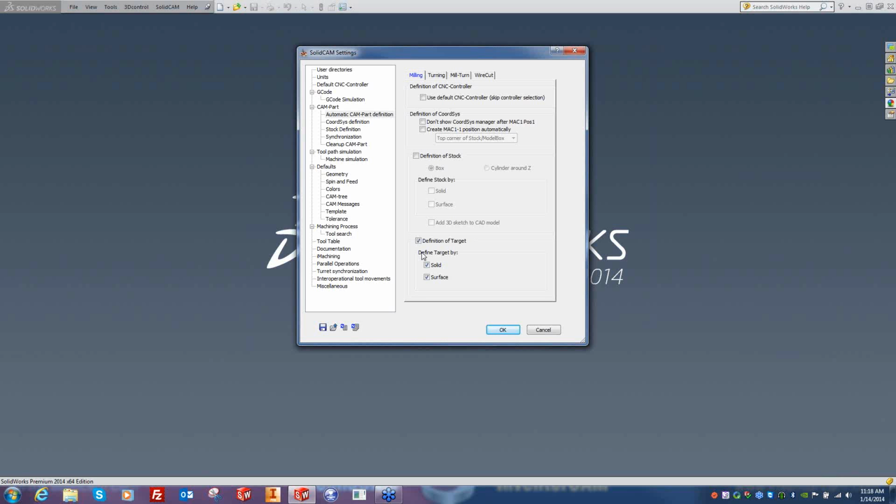But the part that you're working on is called the design model, and it's in perfect reference to the original. So if anything changes on the original, it updates the design model automatically. So, like I said, most of you probably will work with just one part at a time, and then you don't have to think about any of this. It's going to be automatically updated.